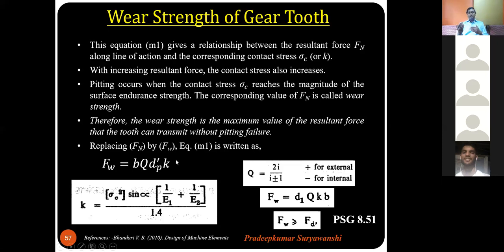And now the next part in the design is we will prove that the wear strength of this particular gear profile or gear tooth is greater than the dynamic load. Once we prove it is safe, then we can say the design for this particular stage, that is spur gears in mesh, is complete. For that purpose we will make use of the equations shown on this slide